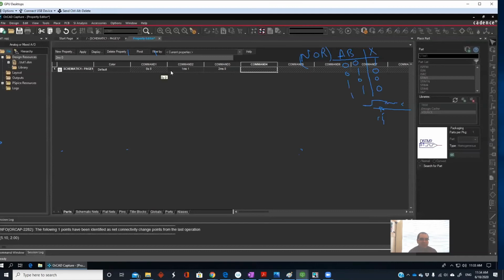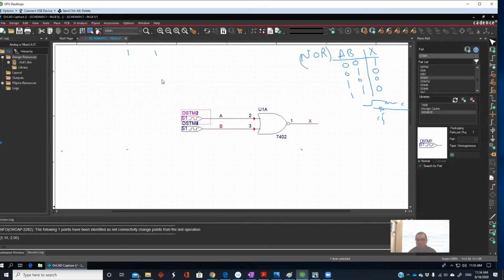All right, so we are done now setting this part. Now what we need to do is also save this. Just close it and it will be saved. What we need to do now is simulate. Before you simulate, we need to add something called a voltage marker.